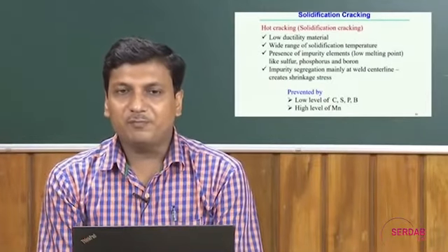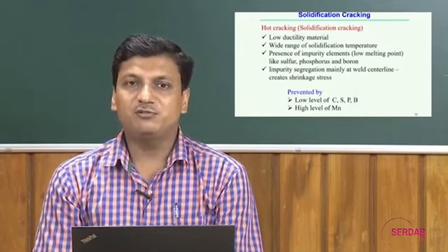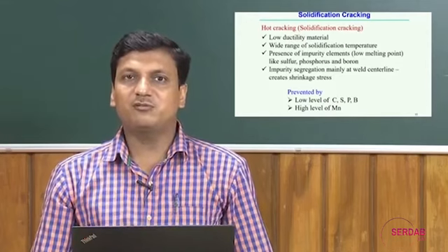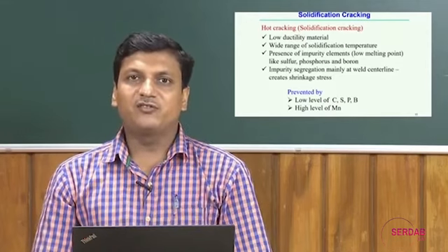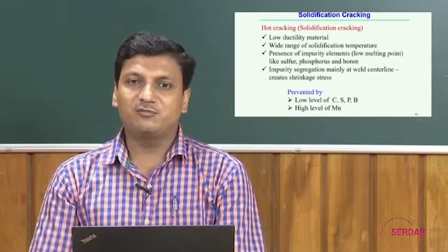solidification cracking. At the same time, a high level of manganese also helps to prevent solidification cracking, because the presence of a high amount of manganese neutralizes the effect of the low melting point elements like carbon, sulfur, boron.